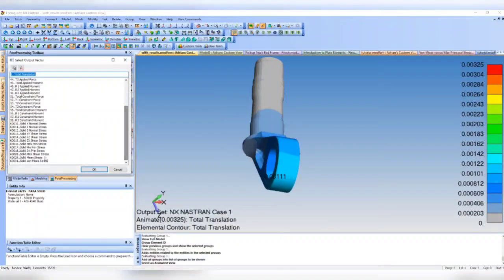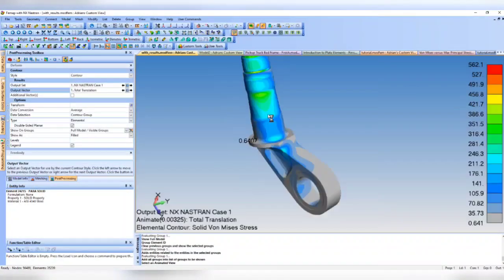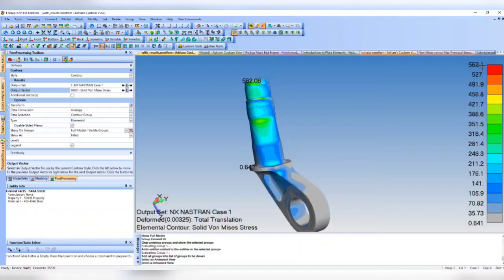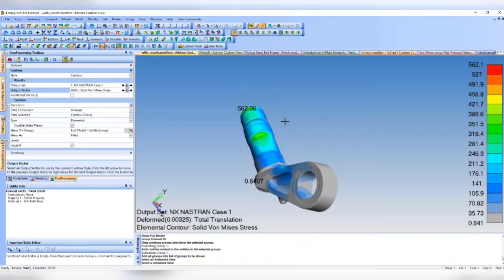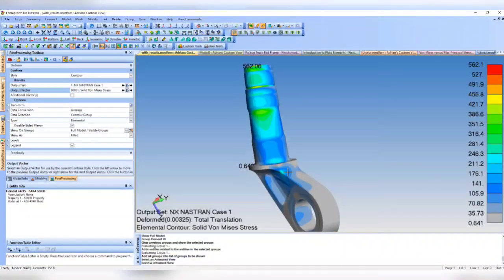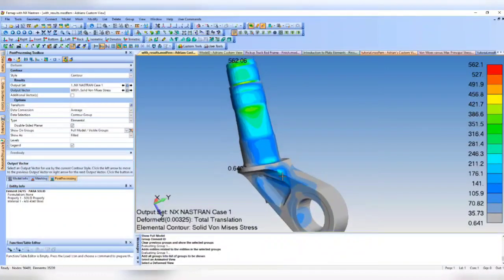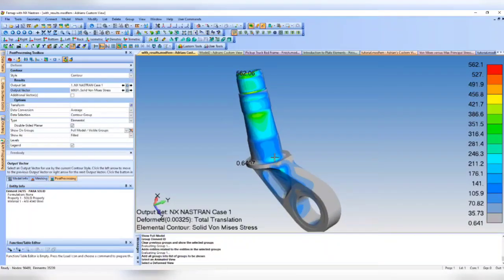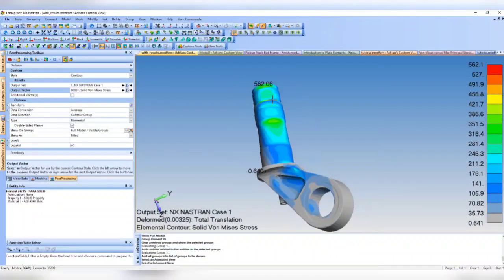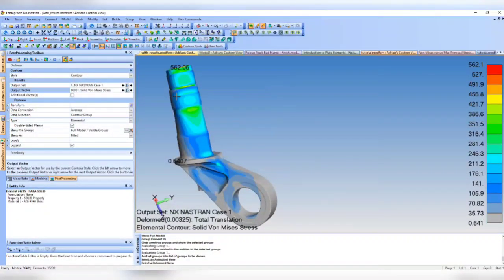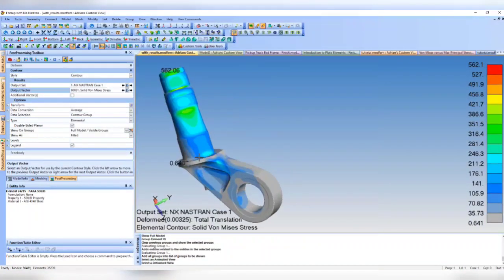Next thing I usually check is the von Mises stress. And the von Mises stress, this is what it looks like. So obviously the more colored it is, the higher stress value. And this is important because you can determine peak stress levels, especially at KT areas, like stress concentration areas. You can see where it sort of lights up. And then in the industry, you can do some durability crack growth analysis at those KT regions. So this is kind of like what the von Mises stress plot looks like, just basically telling you where the peak stress levels are on the structure for that boundary condition and load.